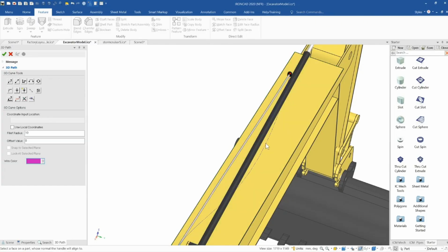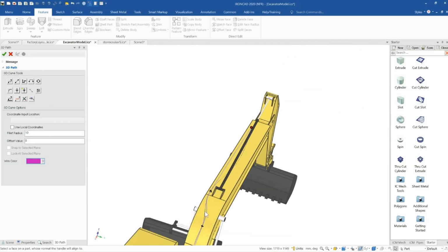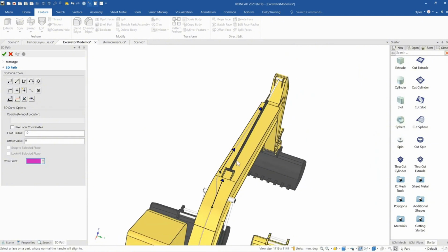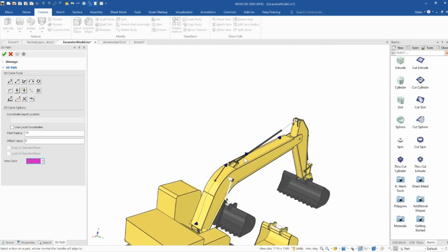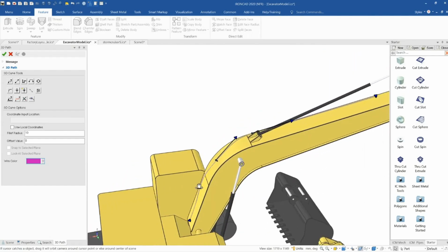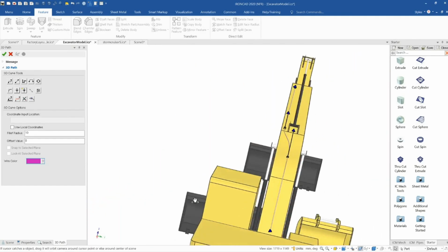Oops, I'm dragging that point around now. But as you can see, you can use those arrows to align the 3D curve as well. But in this sort of case with the hose, generally I'd prefer to do it with the point option with the triball. It's a little bit simpler, and a little bit faster and easier to do.